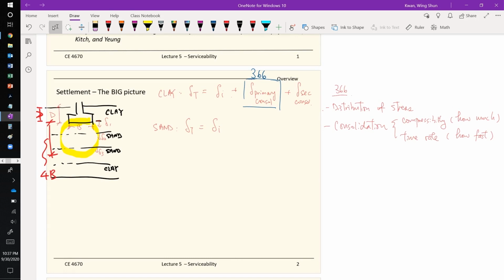In order to do settlement analysis, you need to understand well what type of condition it is. Is it drained or undrained? Because that affects the parameters you use. Even for the same design problem and the same site, if you have different drainage conditions, drained or undrained, you will have different answers, coming from different parameters.